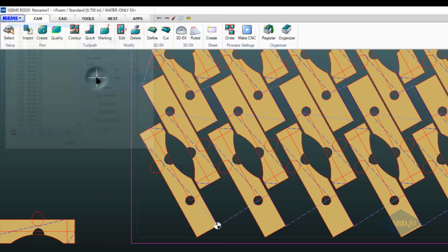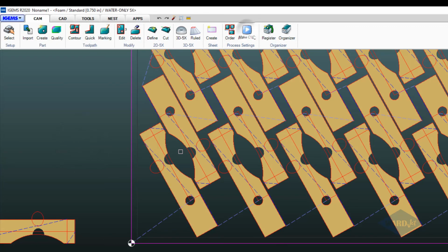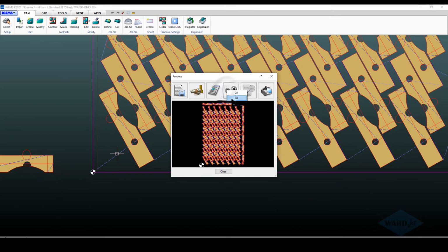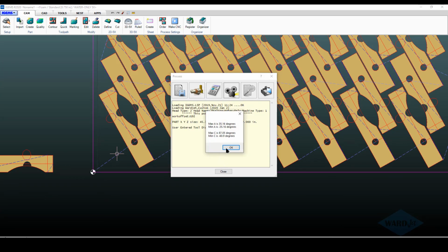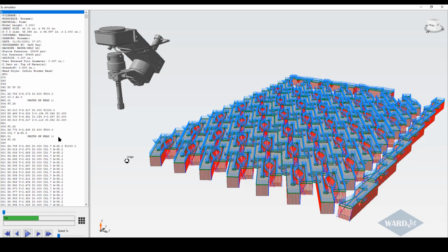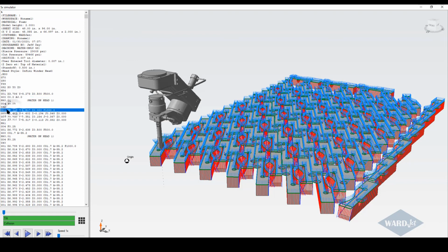And we'll go back and stick this on the corner of the sheet, but we want to change this Z to be 2, so you click on this 2D, 3D button and can put in your 2 there. And now our Z values will be correct. So now at the beginning of this cut here, it's going to wrap it over and then come down to a Z height of basically 1/2 inch off the material where we want to start from.